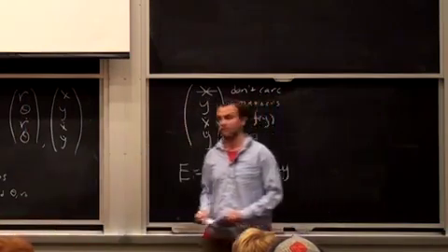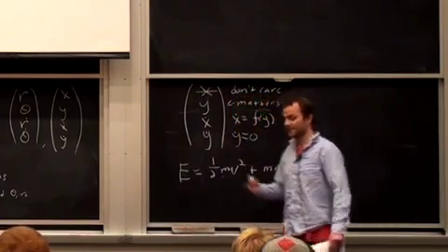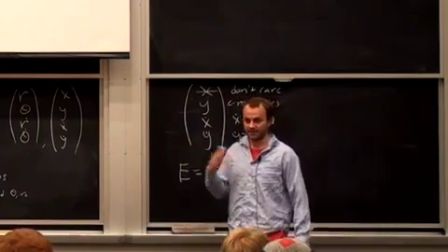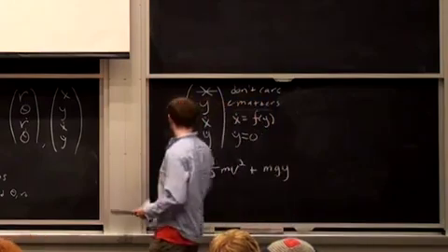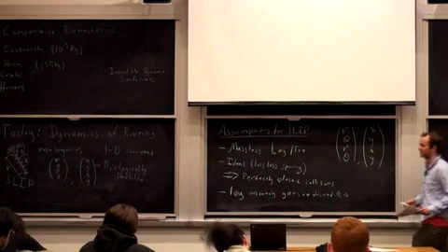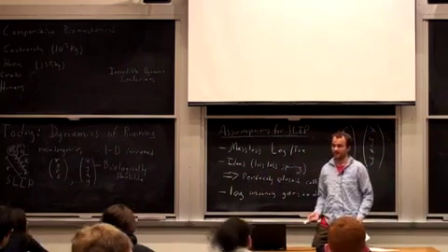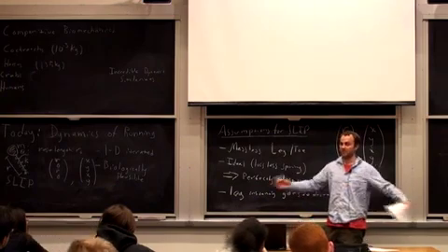Why don't you care about x again? Because that doesn't affect the stability of the system, right? If we're trying to get somewhere, hit a target, then we have to look at x in our controller. But because x doesn't figure in the dynamics anywhere, it doesn't matter. Sorry, this is something I should have mentioned in the beginning: it's not going downhill or anything like that. So how far it goes in x doesn't matter. The dynamics are going to be the same, invariant to that.